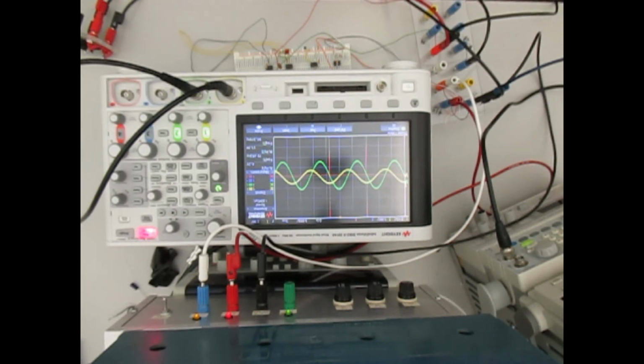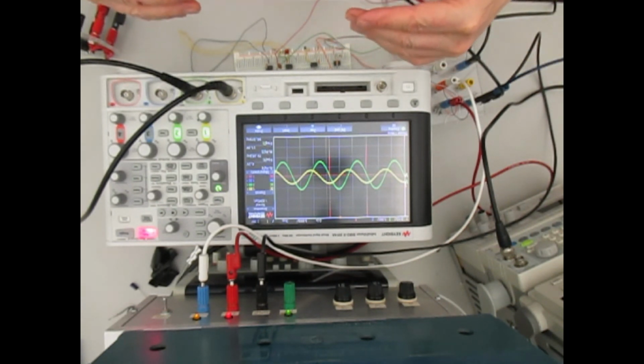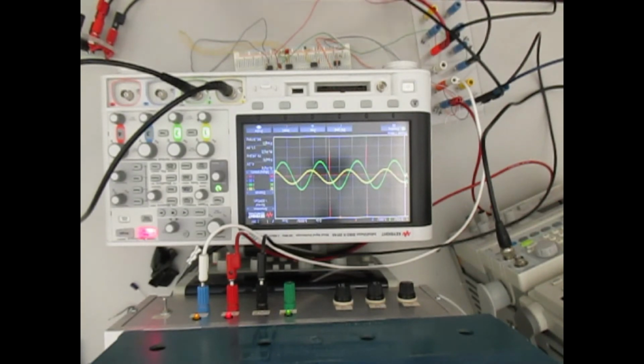And so if I had a PID controller, if that's what we were going for here, I'd have my proportional, my integral, and my derivative, and if they're all inverted, the other amplifier setup we can use is called a summing amp, and so you would add those three together to give you your final output of the controller. And if you added those together through another inverting amplifier circuit, you got your proper output and everything is good.